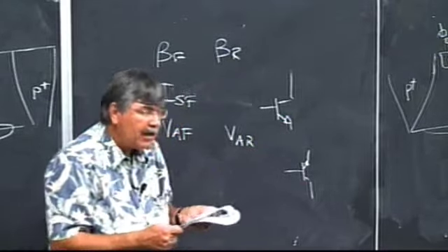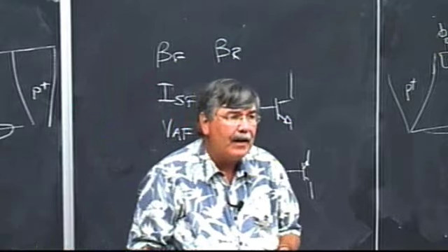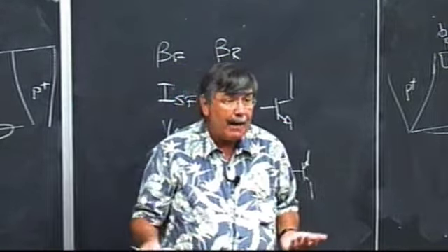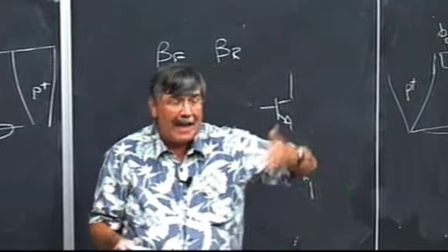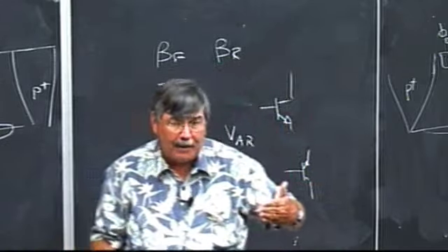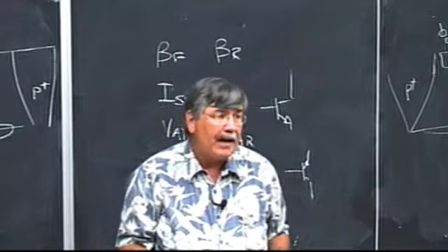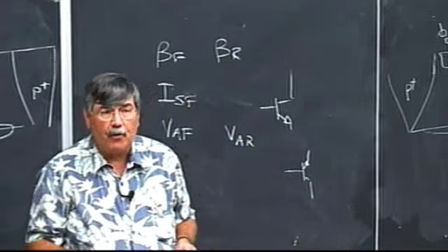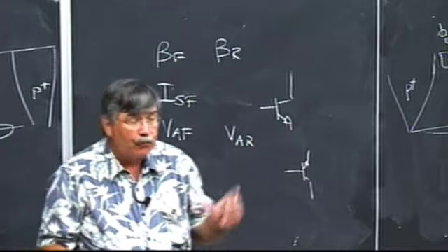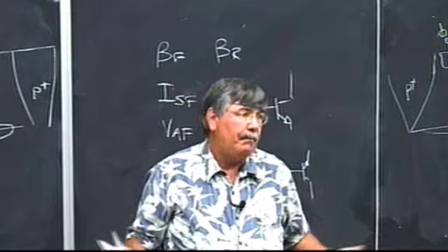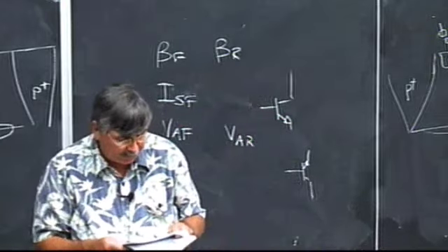We have things that tell us how much base resistance we have. That's modeled in series with the base terminal. And we've talked about why it happens, right? Because of the resistance between the active base underneath the emitter and making its way out to the contact. So a typical value of the base resistance might be 100 ohms. But if it's a really tiny device, it might be 500 ohms. So there's trade-offs. Different designs of transistors are going to give us trade-offs.